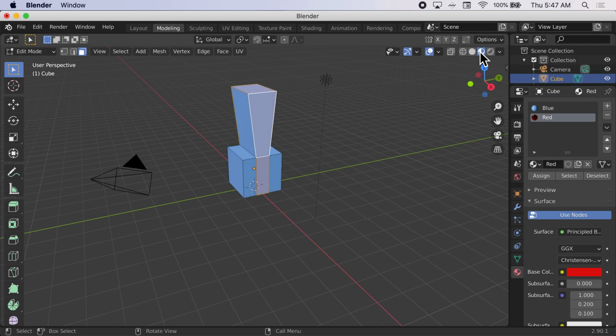So if in the top right, you go to the second from the right. The far right is going to do a lot more intensive shading, like using the lights and so forth, to make more intensive use of both your CPU and your GPU. We want to keep it in this mode right here, this development shader, which is really easy on your computer because it's not nearly as intensive, but it does show you the colors. So we're going to use that.